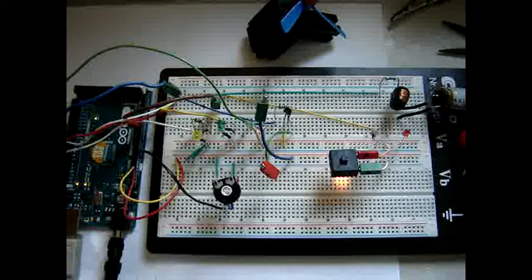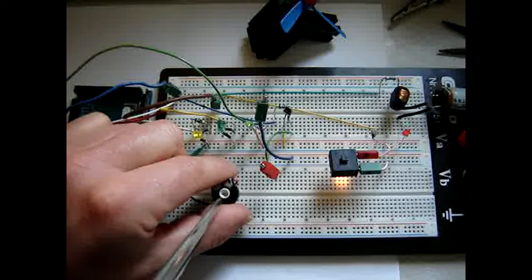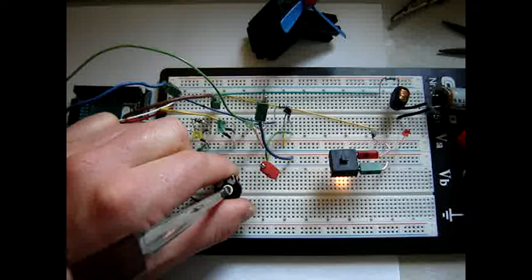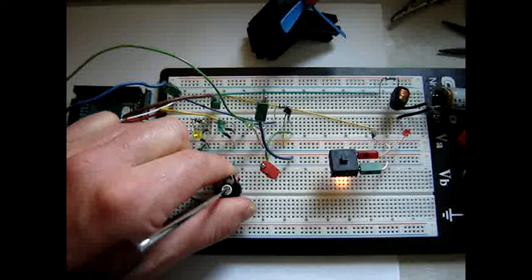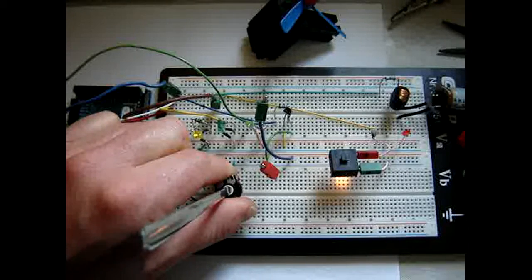After checking the wires, it turned out that one of the wires of the capacitor was not completely fixed into the breadboard, so now it should all work.